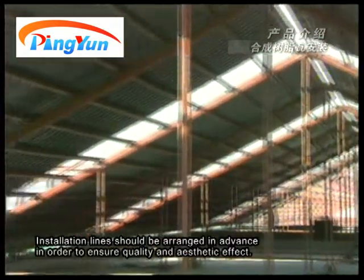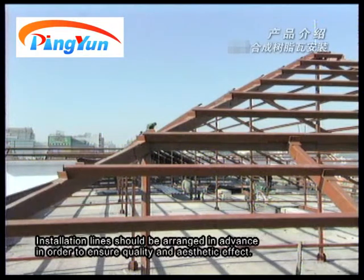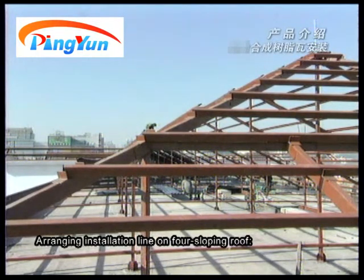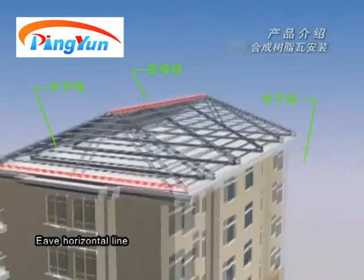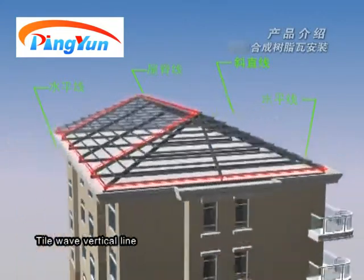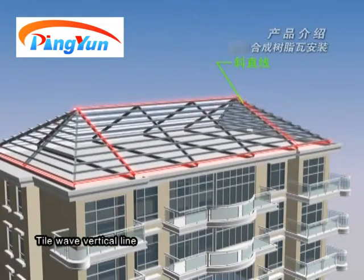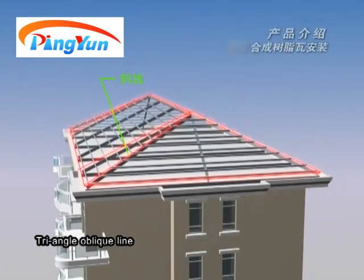Arrange installation line. Installation lines should be arranged in advance in order to ensure quality and aesthetic effect. Arranging installation lines for a sloping roof: top ridge line, eave horizontal line, tile wave vertical line, triangle oblique line, triangle midline.